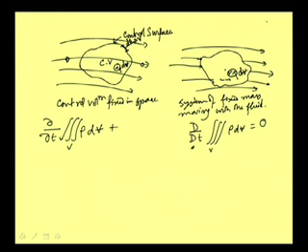So, what is going out through this small surface, we can have in unit time, because we are talking about per unit time. What is going out in unit time is the surface area into the velocity, which will be the volume of flow going in unit time, and if I multiply it by rho, so rho V dot dS, where V is the vector velocity and dS is also in vector notation. This much is going out from this part, and if I integrate it over the surface,